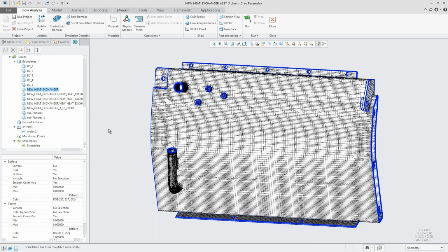Like I mentioned earlier, in areas where it's going to be a bit more complex, so you have some curvature, it's going to build out the mesh to be a bit finer in those areas. And then any area in the middle, like you see there, where it's going to be a bit more flat, a little bit easier to approximate, it's going to start to spread out that mesh a little bit more. That's what you want. It's going to make our study go through a lot smoother.